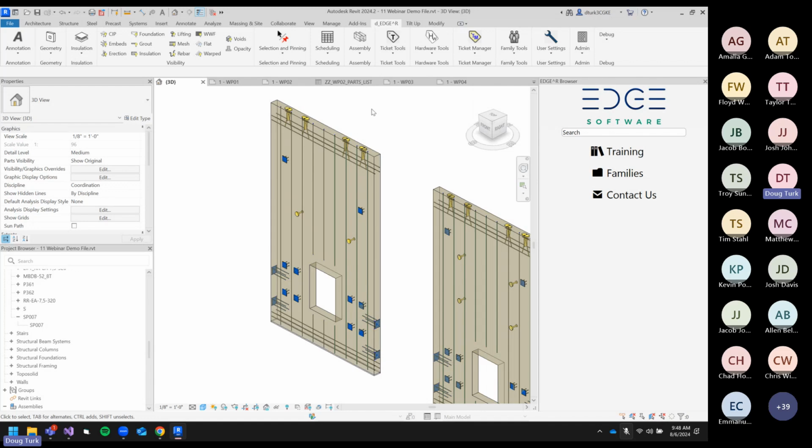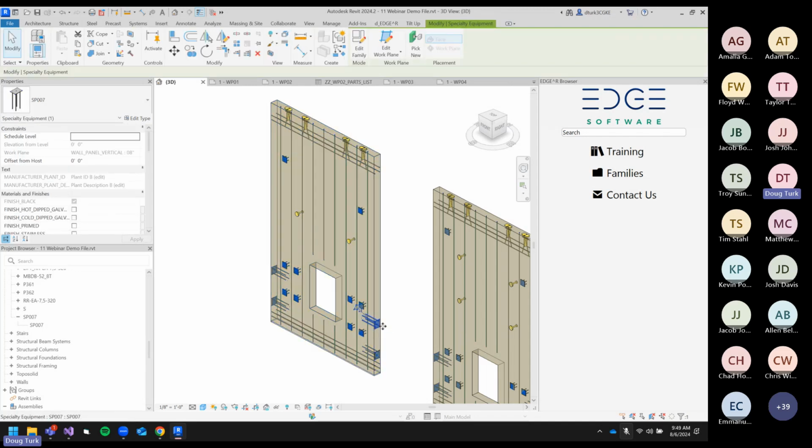But the first thing that I need to discuss with hardware details is the changes that were made to the project shared parameters tool in order to make hardware details functional. So at its core, what the hardware detail utility is doing is it's taking a piece of hardware that you select, copying it out, and creating an assembly for which you can create sheets, views, anything that you would normally do with a piece ticket, except now it's for a hardware element.